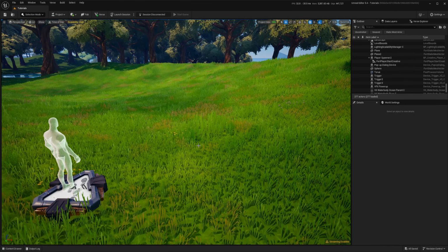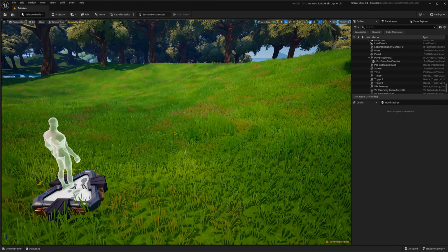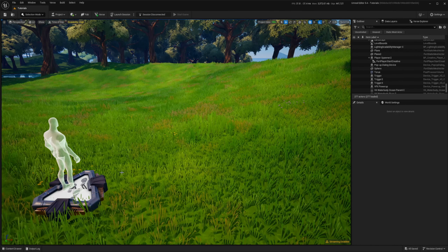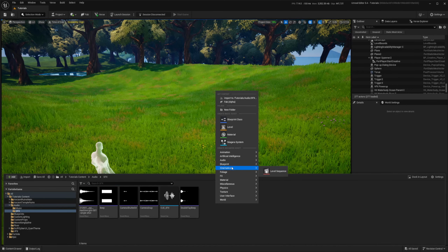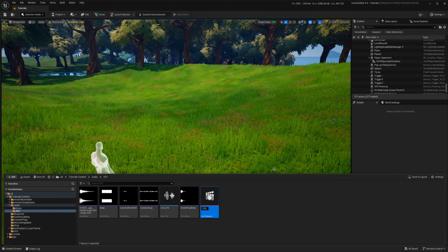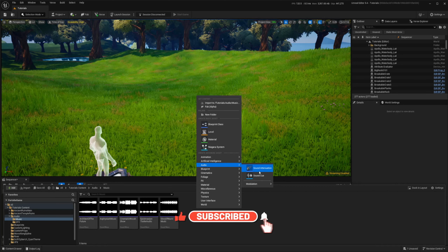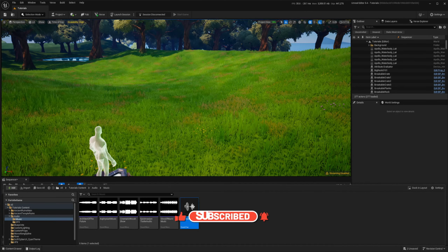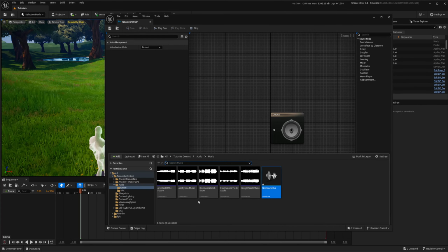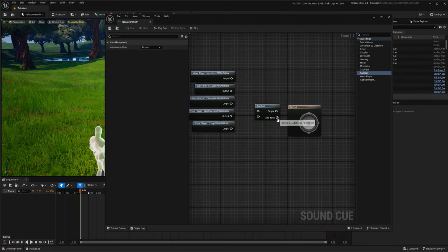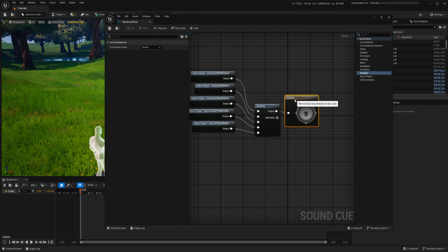So now, as we covered how to play audio inside of VFX, I will show you how you can play audio without an audio player device or radio device. Let's create a level sequencer. We will create an audio Q. I won't name it right now. Let's drop our music. Pick our random node and connect to output. Save, and we have it.